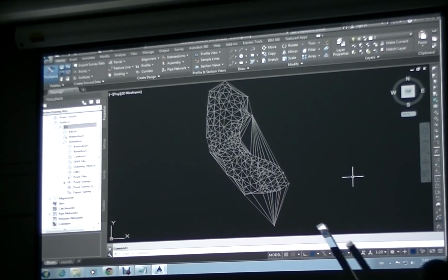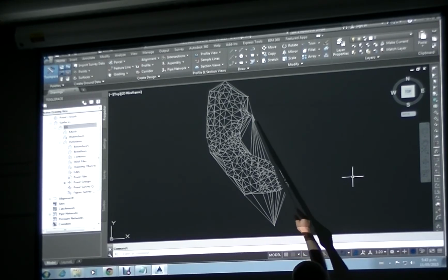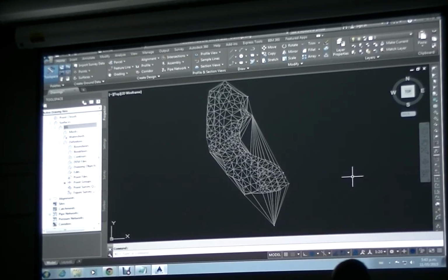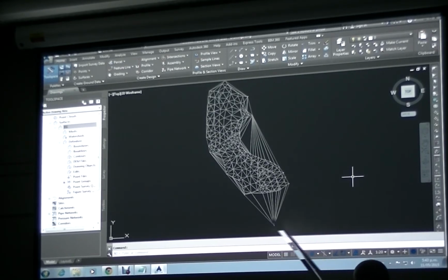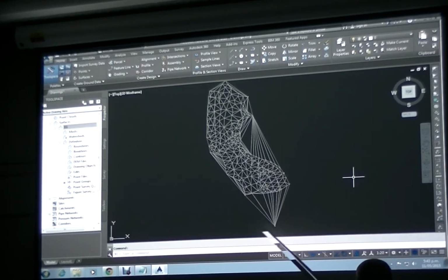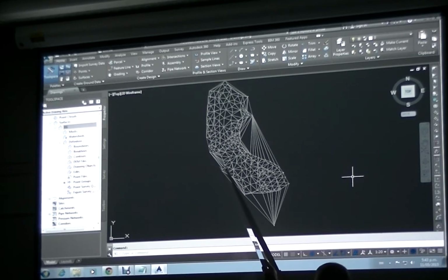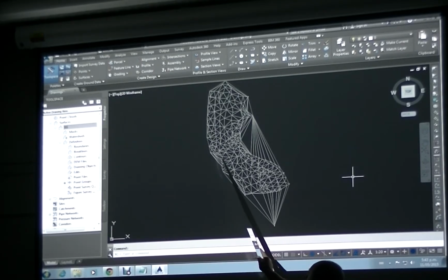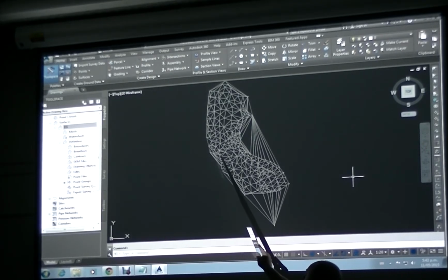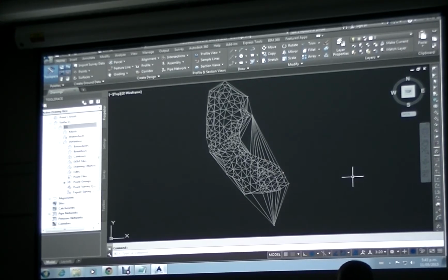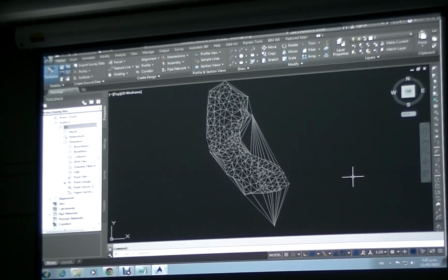The problem with this is you can see that it's shooting across the pond. We haven't got data in this area, so we shouldn't have contours. And same down here, this is just a reference shot to something. We shouldn't have contours through here because we don't have enough data. Even up in here, we haven't got any really shots, so we probably shouldn't have contours through here. It's up to the designer to make the call, but I would generally try and cut all those out, alright?